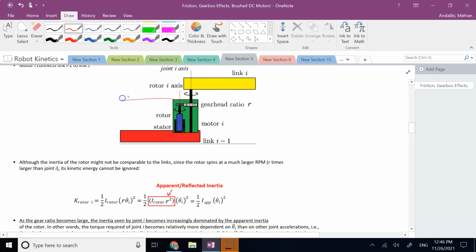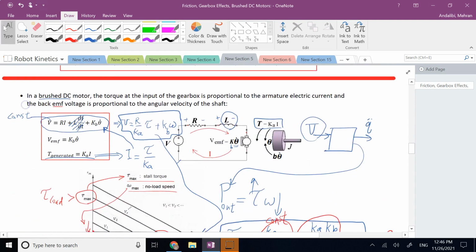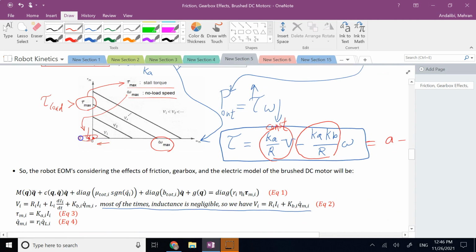If you remember the static torque, tau is J transpose times F, where F here is the force of gravity only. So if you multiply the transpose of the Jacobian by F, that is the torque at the joints to just keep the robot upright and compensate for gravity. So you always need at least this much load on the motors, so you never run in the area of zero torque.